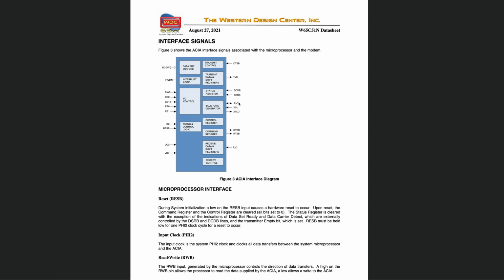And then inputs and outputs for flow control and device detection. These are part of the RS-232 communication standard, which we're not going to be implementing with the circuit. I will only be using the transmit and receive, and I will implement software flow control because the UART interface I'm going to use and talk about later in this video only has transmit and receive.